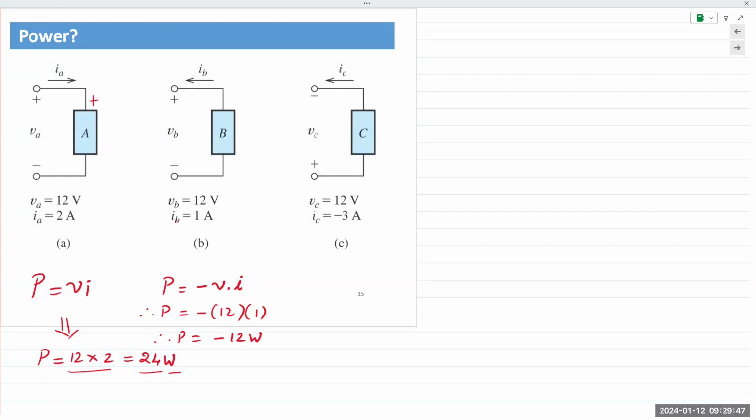And then here we circle back to that question that was being asked earlier. So what is the power equation we use for C? P equals VI because it is positive, right? It enters the positive terminal. And so P equals VI, but the value of the current given to us is negative. So we simply enter the negative value here. We do not mess with the direction of the current. The current direction is what it is shown in the figure. We are not concerned with that.